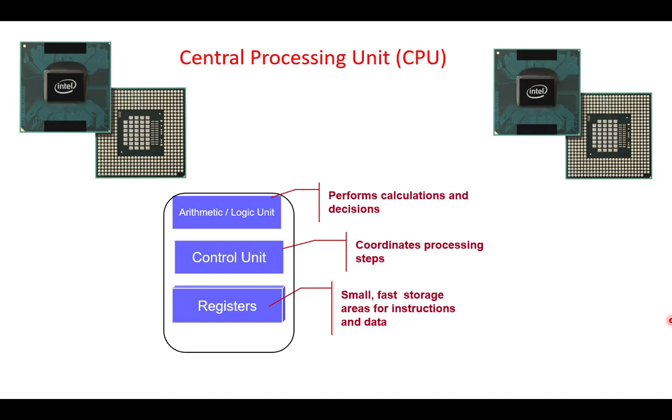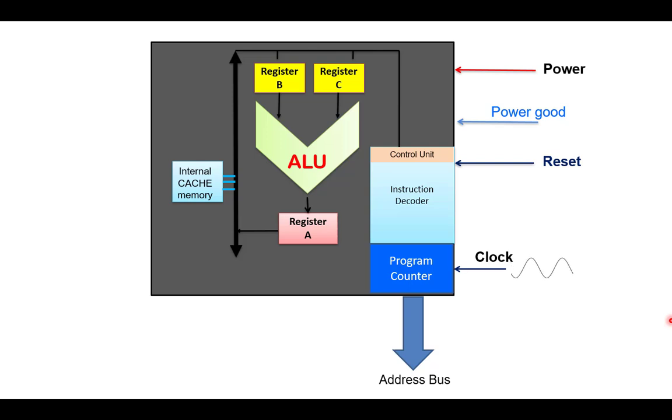Okay, now we'll go ahead. In this session we'll see how the CPU works theoretically. First, what are the things required to run the CPU? First, the CPU requires different levels of power or voltages. In a modern-day CPU, three levels of voltages are required. That is VCCP, which is around 1.05.